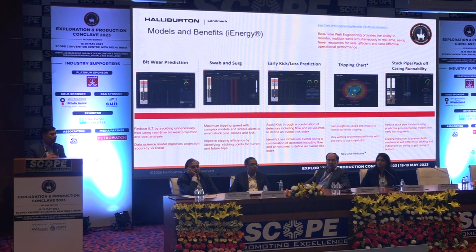And of course, we are doing a worldwide pilot project to enhance and calibrate more based on ML and AI technology. We have something which is early kick and loss prediction, which is based on your return flow, and it helps you to eliminate the use of Coriolis devices, like we have the EKD type of equipment. This model will help you to eliminate that, and you get direct results from the flow line, whether you can stop that kick or loss.